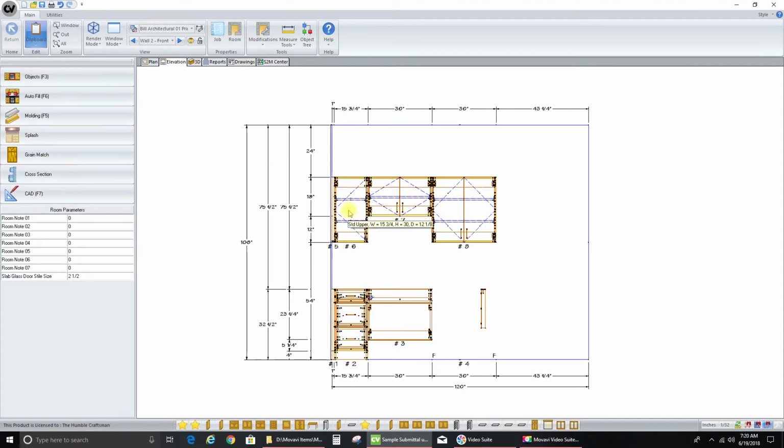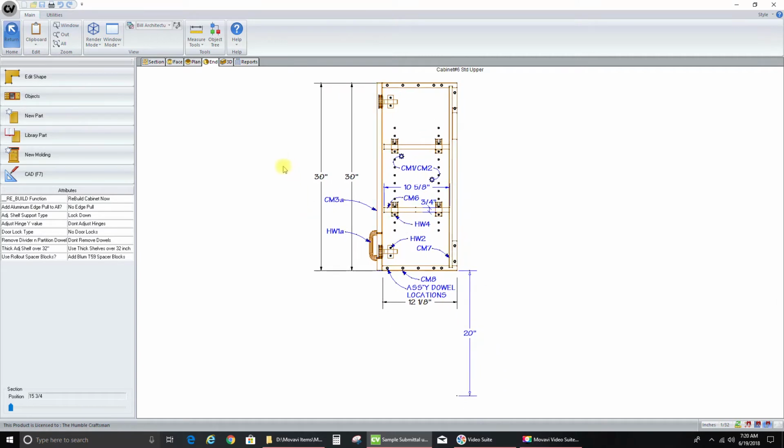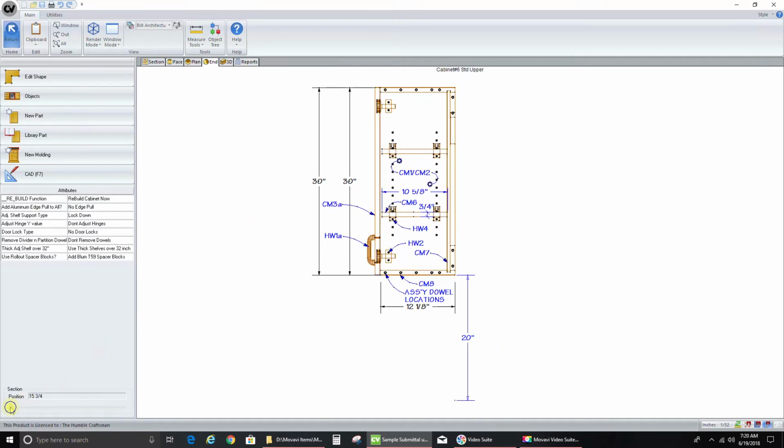And we're going to use this one here, because it has an unfinished end and a finished end. And I want both of those items to fill out on the legend table when I'm done. So I'm going to slide this section bar over just a little bit so that it'll still be on the right side of the handle. And I'm going to send to drawing.